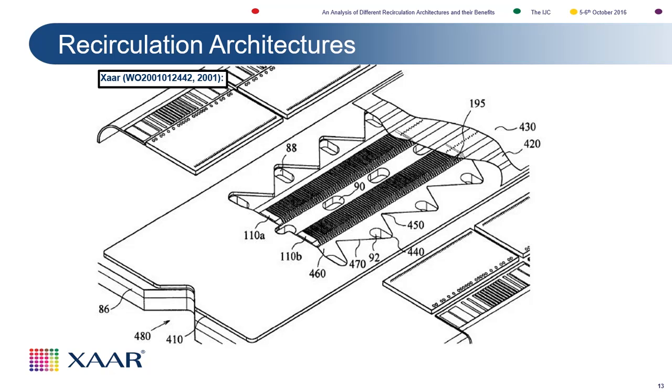So you can see here where the ink comes in through the central inlet into the submanifold. The submanifold is directly in contact with where the channels are, so there's no restriction there. It goes across the chamber, which is the channel structure that you see, and you can see the nozzles, and then it returns to the submanifold. So really quite a simple recirculating architecture.